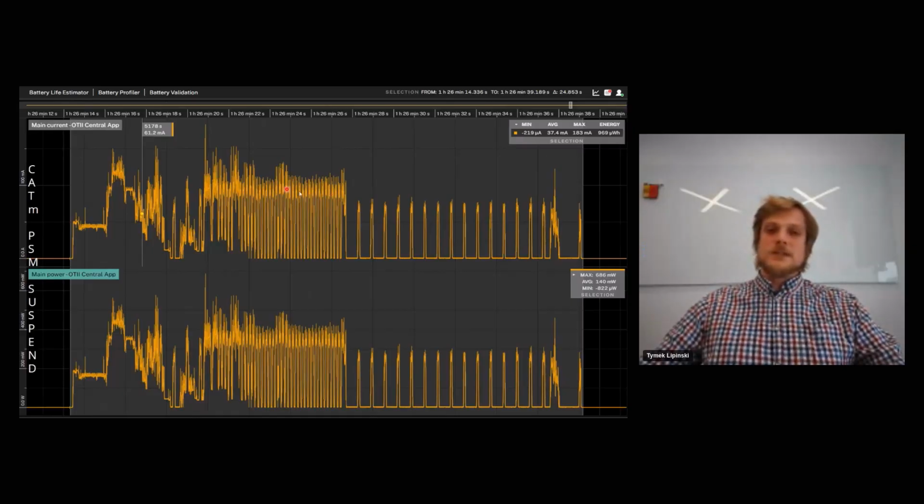When we have not sent any data or exchanged any information, the network releases the RRC connection here, so the current consumption plummets. Then we just listen to paging, paging, paging. All the way here, we prepare for PSM suspend because there was no data traffic, no activity.